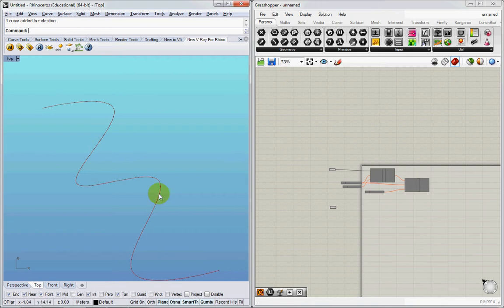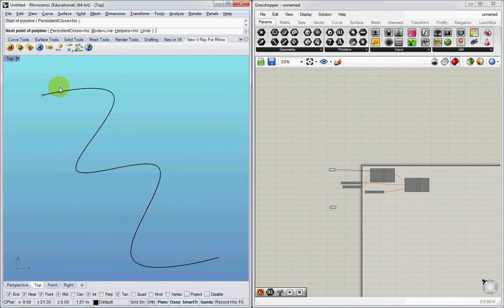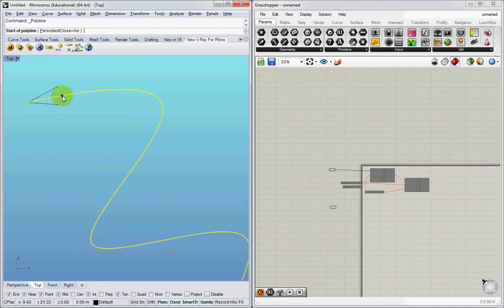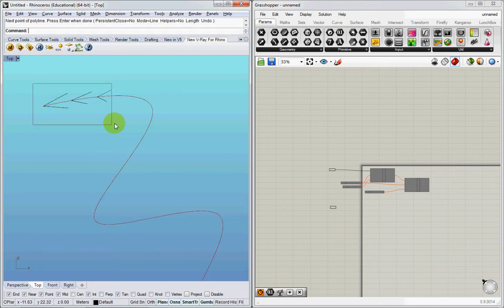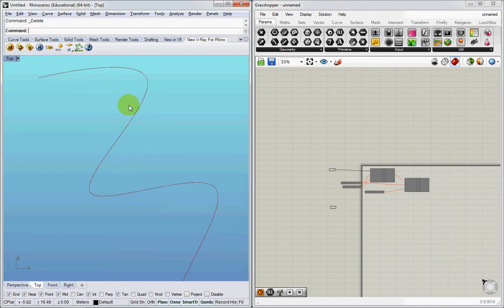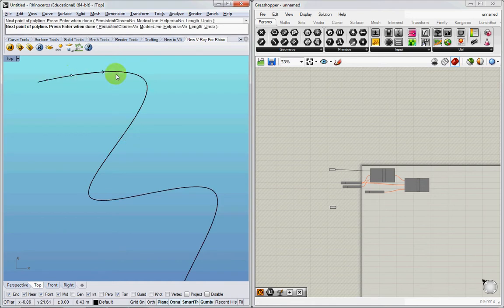So right now I have a line, and let's say in my drawing I want to create, using line work, a line that is not so clearly defined, or I want to create a fuzz around it. One way of doing this could be that I sketch this kind of feathery effect onto it. And in Grasshopper, the best way to do these things is to think it through. What does that mean? First I divide it into a series of points.